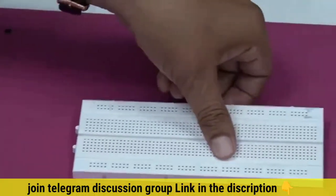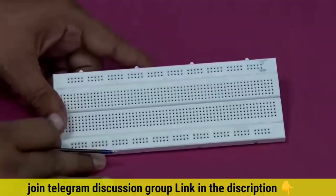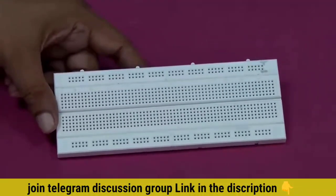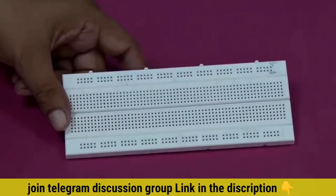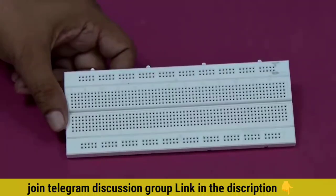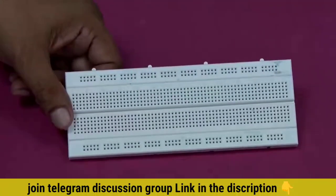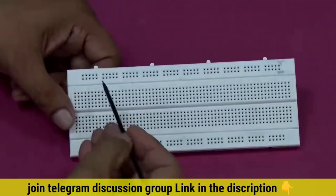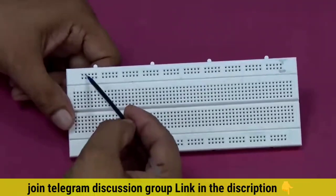So, now Ranjit has to help me. As I said, the negatives of the battery, the black terminals of the multimeters, and the emitter are all connected to the zero potential line. They have to be connected to each other, which we will be calling zero potential. So, on this breadboard, I will be using this line here for that zero potential.